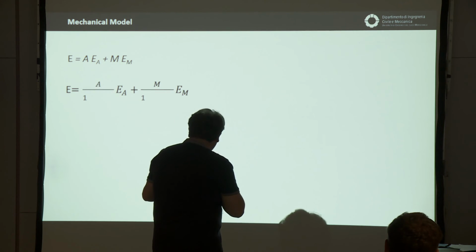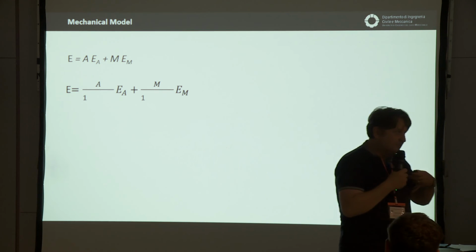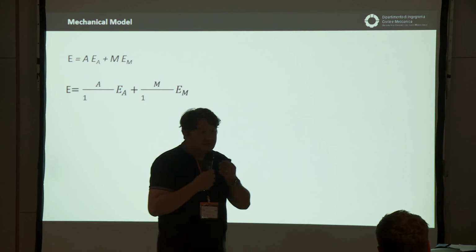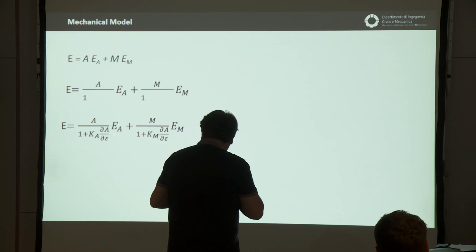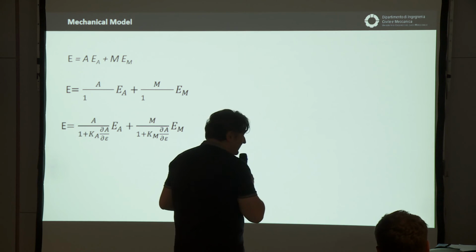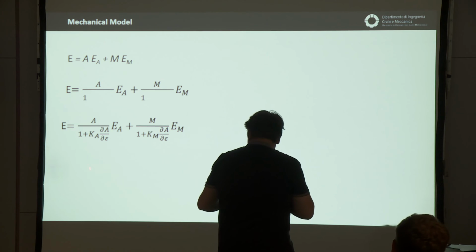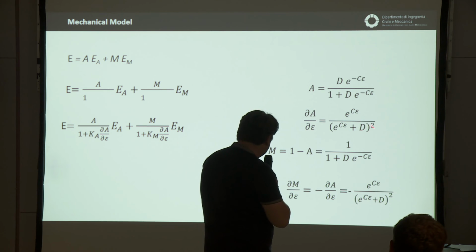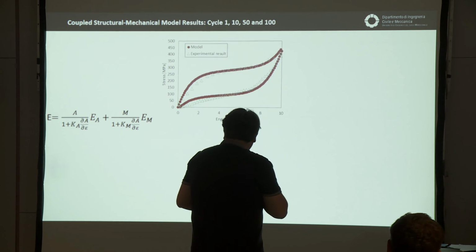It doesn't work in this form because not all the austenite participates in the increase of mechanical stress; part of it uses energy in the transformation. So, eliminating the quantity of austenite that is transforming into martensite, you have a different form like this for austenite and martensite, where the austenite and martensite are calculated and the derivative is easy to obtain, and the results are this.